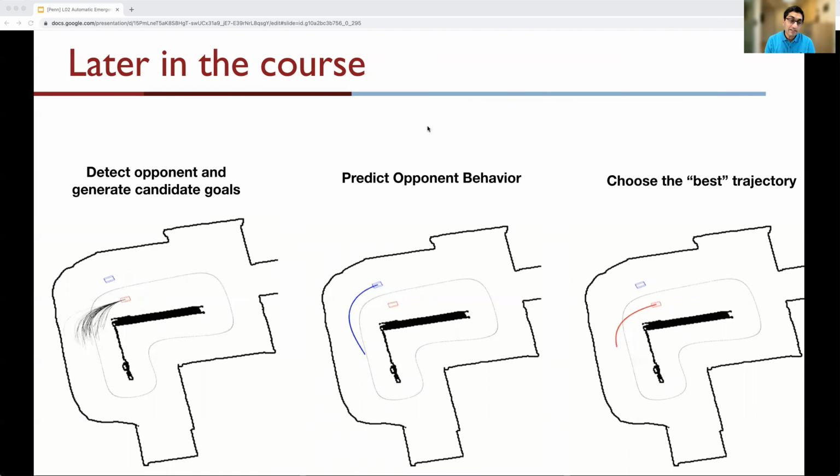So as we start to race against cars later in the semester, you learn how to do overtaking, perhaps even with some drifting. And in order to satisfy this safely, you will build on these AEB basics and add object prediction for possible trajectories the opponent could take, using the vehicle's dynamic model with tire models, cornering stiffness, and also some way of estimating the opponent behavior and the potential for collision. You will then design planning algorithms that will need to decide what is the lowest cost trajectory that can avoid a crash, but successfully execute an overtake maneuver.